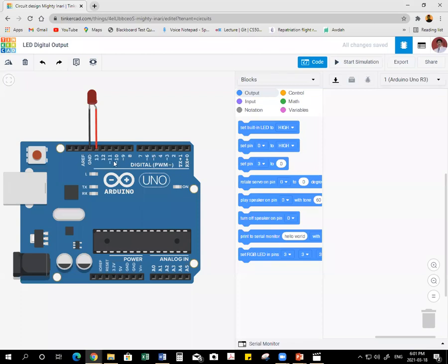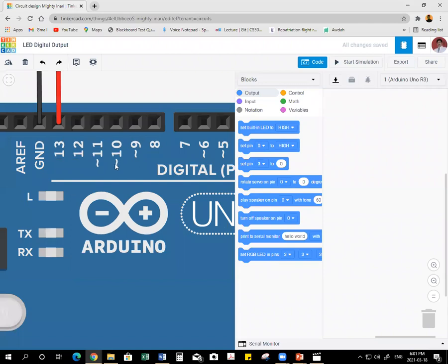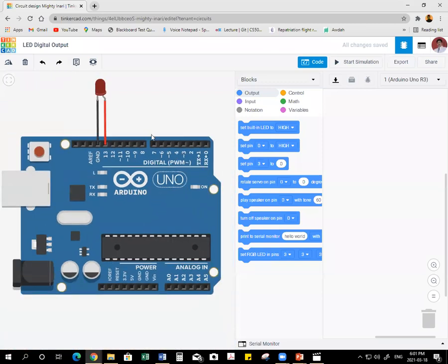And in between, we have pin number 3, 5, 6, 9, 10, 11. Some tilde sign is there. If you zoom in, what is it showing? It is showing a sinusoidal sine wave like symbol. So it is called an analog pin. In the next circuit, we'll study what an analog pin is. First, we'll see the output of the digital pin.